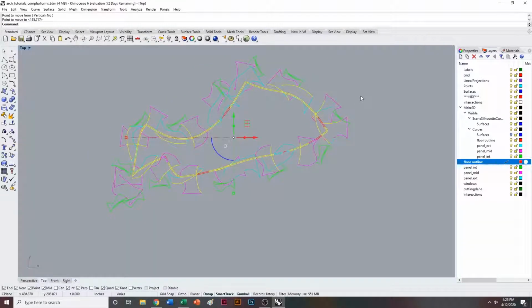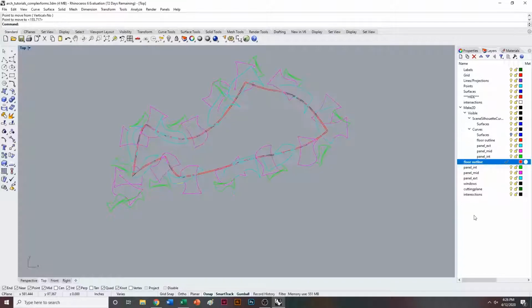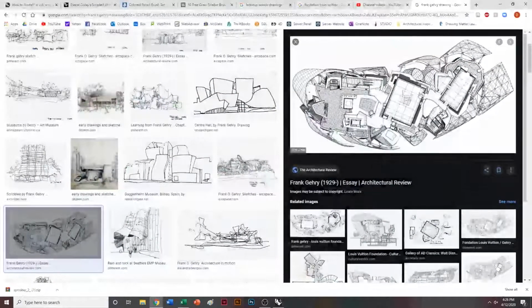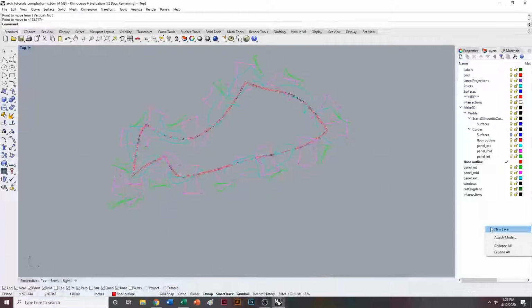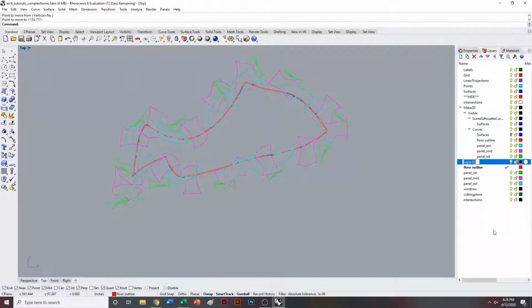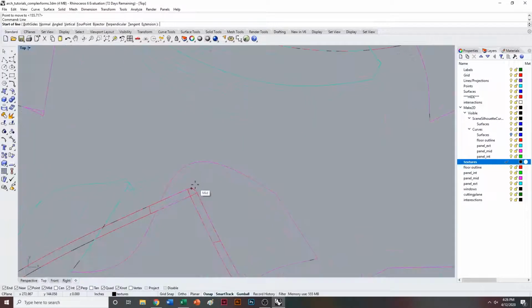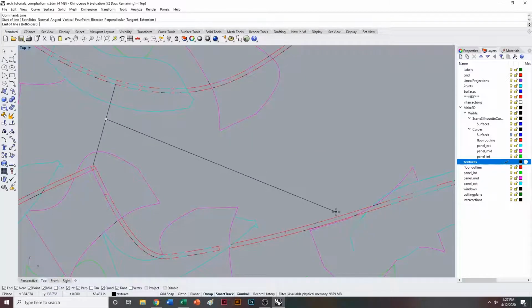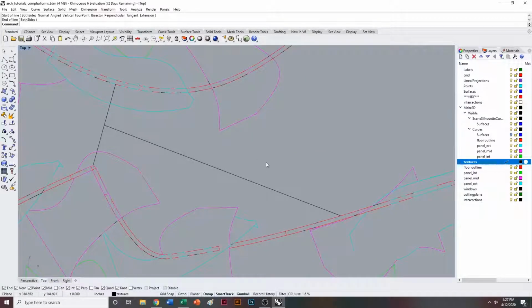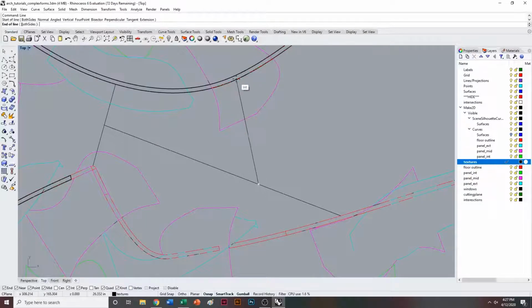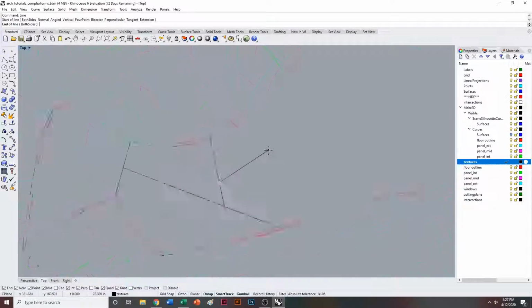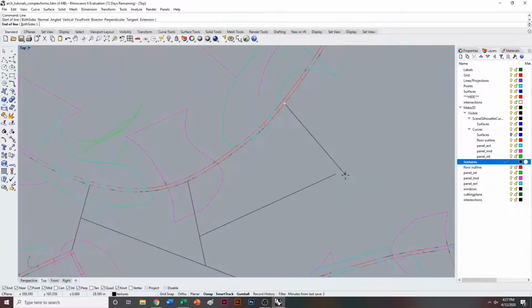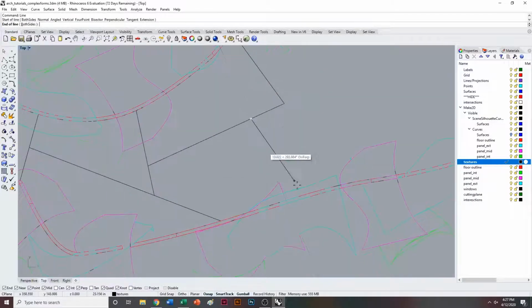So from here, the last thing that I want to do in Rhino is start to play with some of these textures that he has going on. Go ahead and make a new layer and type in textures. And then I just want you to type in line and basically click and drag from one point to the other across the screen, like so. Almost as if you were looking at farms from above, how they have a very distinct kind of squared-off pattern, also what you see with city maps and things like that.